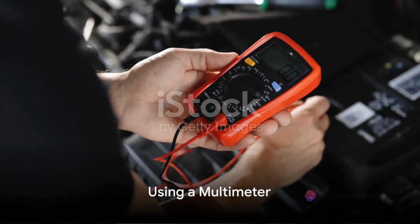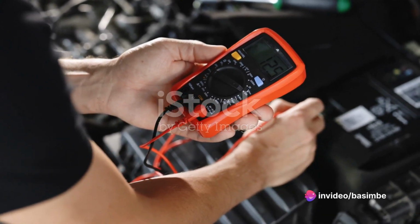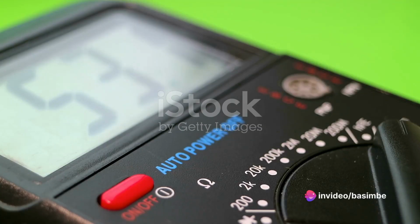A multimeter is a handy tool for measuring voltage, current, and resistance in a circuit. Remember to set the meter to the correct range before taking measurements and to connect the probes correctly, red to positive and black to negative.